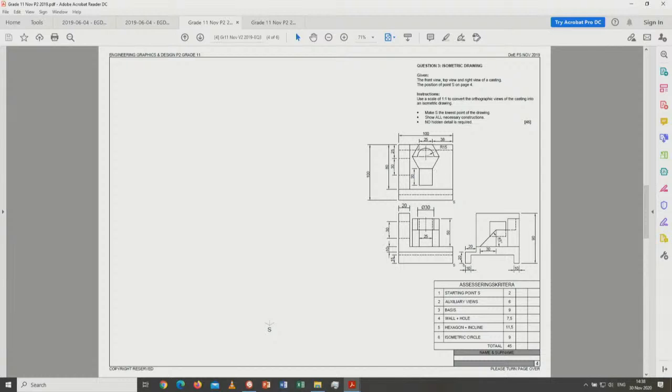You can see the hexagon, so you will immediately know that there are non-isometric lines, because you know with solid geometry that this corner will be 60 degrees and that will be 60 degrees, so you can't work on 60 degrees to find that view over there. So you will have to a great extent work with non-isometric lines in terms of finding those answers. There's a window at the back, and there's the window at the back over there. This line running from left to right and running from left to right is basically the grooves that form here on the bottom over here.